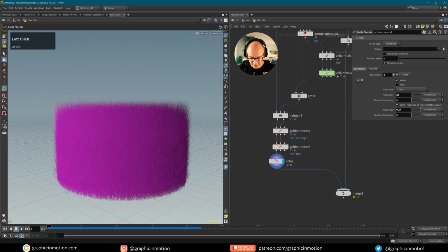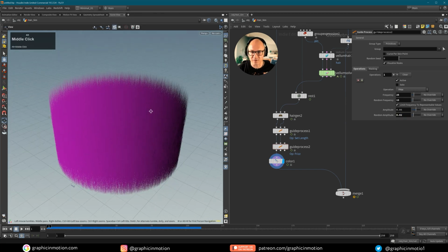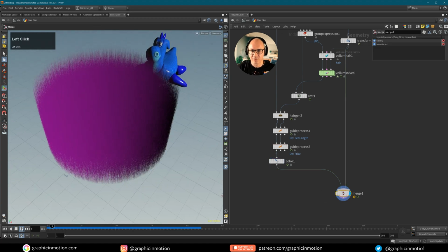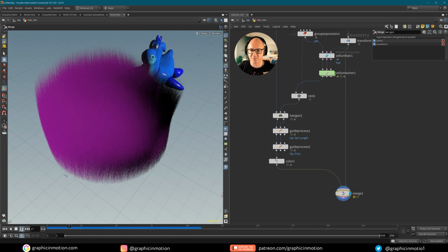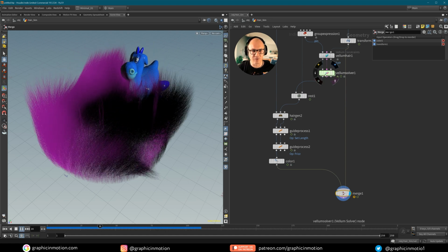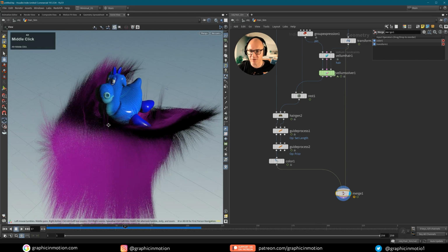So we don't want to do that. We want to keep this quite low. And then you can also do some random amplitudes, maybe 0.2, and random frequency, maybe like 15. And you will get something like this. And I think the amplitude 0.02, I should say, otherwise it's way too high. Yeah, we get something like this. And this could now look also quite nice. So these are just a few basic operations that you can do after creating your simulation. And if you save the simulation to disk, which I did not do, then this, of course, will get a little bit faster.